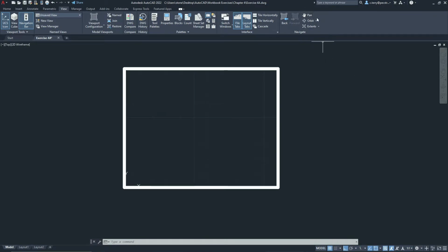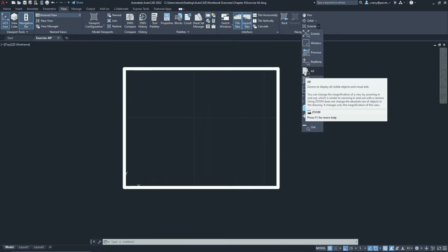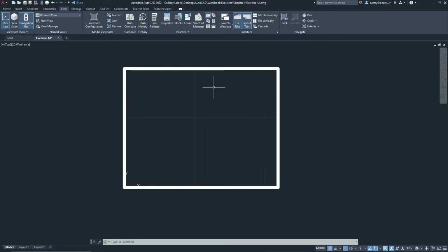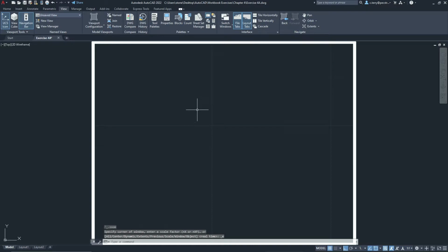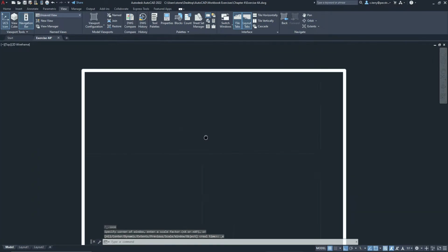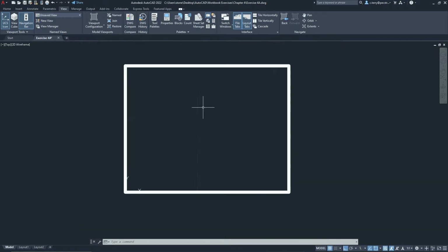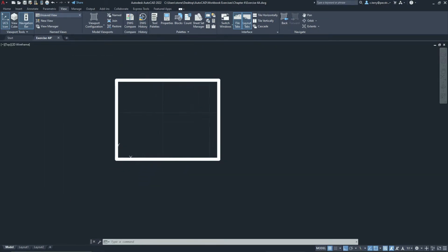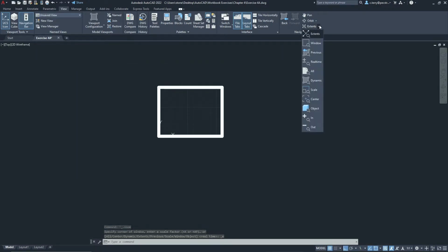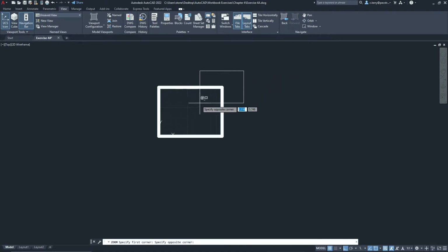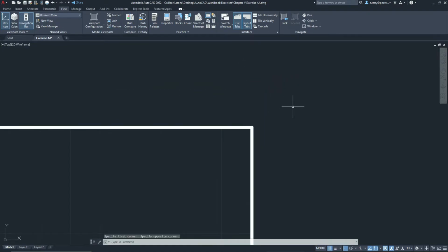So from here, you can navigate by doing extents, which is really what we're going to talk about today. And it's the zoom command, really, is all you're doing. And basically what that means is it's a more accurate way to take the roller wheel on your mouse and go in and out. If I double click, that's a command. If I click and drag my mouse wheel, that's a command. Again, holding it, double clicking, zooming out, zooming in, that sort of thing. All extents does is the same thing. So if I want to window here, it's going to zoom into that area.